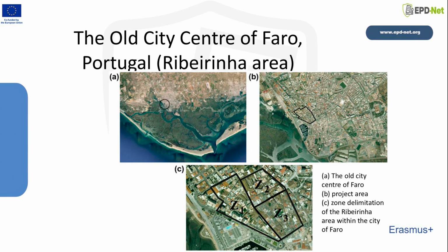The calculated Vulnerability Index (IV) is used alongside macroseismic intensity (EMS-98) to predict mean damage grades (MDG) and generate comprehensive damage scenarios for different earthquake intensities, e.g., VIII-IX. The GIS integration allows technicians and decision-makers to gain a global view of the area, which is essential for planning interventions, accurate risk mitigation strategies, and emergency planning.